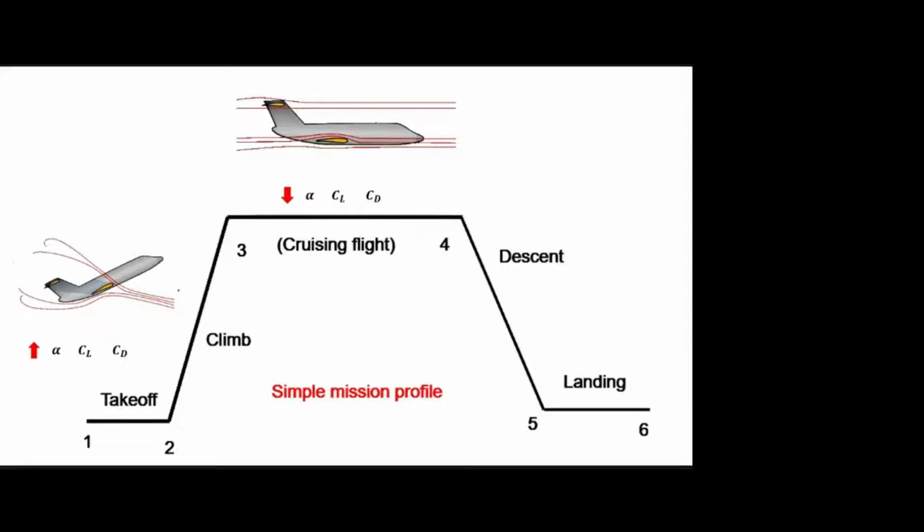And you know, during takeoff and climb, the velocity will be very low. So you know the lift formula, right? Half rho v squared S CL. That is density, velocity, area of the wing, and lift coefficient. This is lift. During takeoff and climb, the flight is just starting, so the velocity will be less, but we need sufficient lift to keep the aircraft in the air.